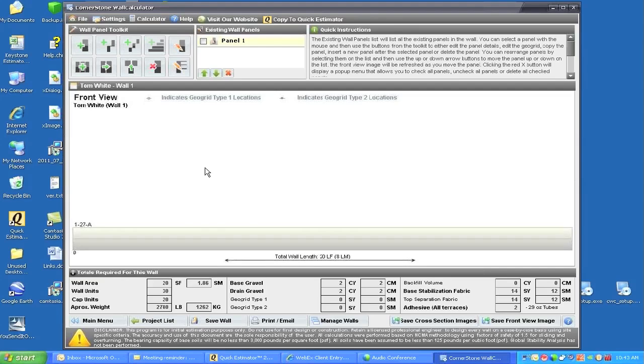So, in other words, the translation between 990 and 988.5 is 1.5 feet. Instead of having those top of wall details, he would just have 1.5 feet, and then he would indicate where the elevation is dropping on the bottom of the wall or top of wall. Those are important things. As you can see from the drawing that we did, the bottom of the wall is dropping, and there are certain points where the top of the wall elevation is changing, and each panel has to have that indication because that's important to the overall calculation, and we'll go through that.